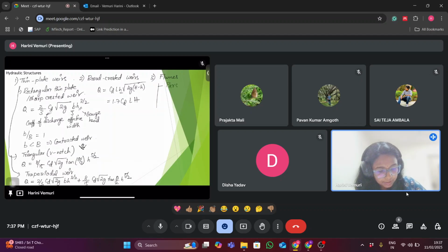Mainly we will be talking about two types. Partial flumes, which will operate with a small drop in head, and it will adopt a Venturi principle. So in this case, the loss of head will be 25% of the loss of head in the case of weir. So also we will have some converging, diverging, and also a throat section within this flume. And the discharge is measured as Q equal to K into H power u. K is the dimension factor and it is a function of throat width. And generally u value will vary in between 1.5 to 1.6.